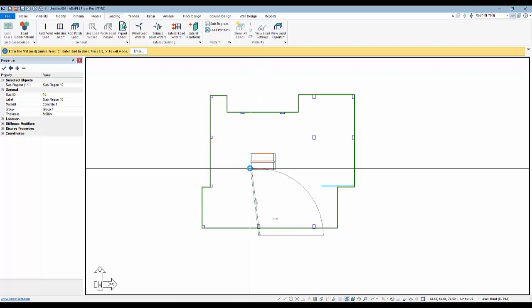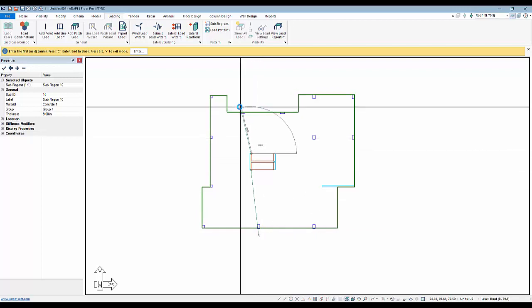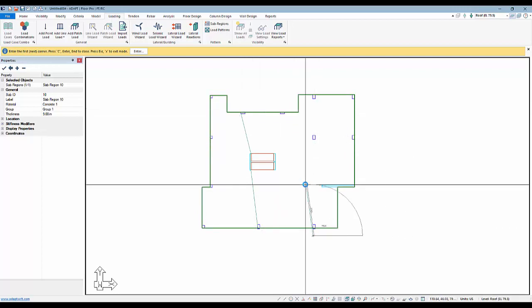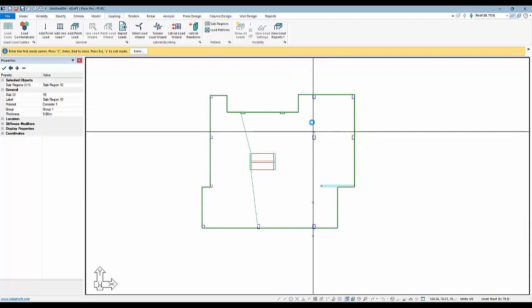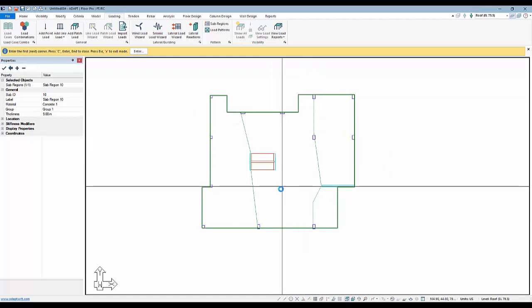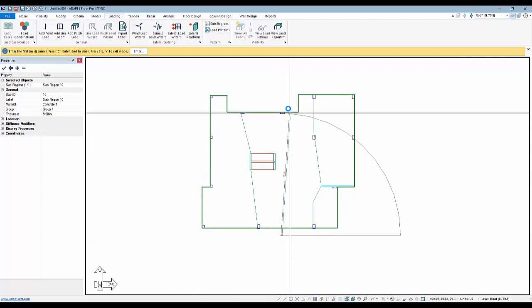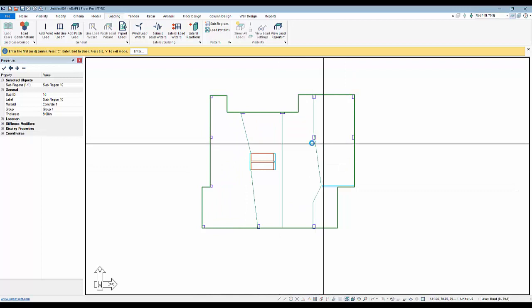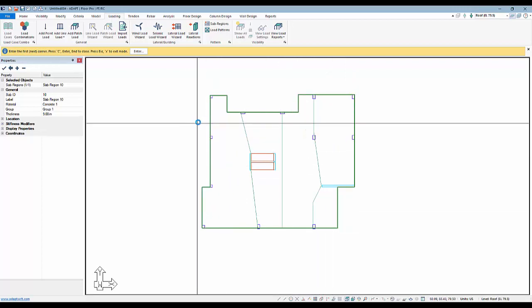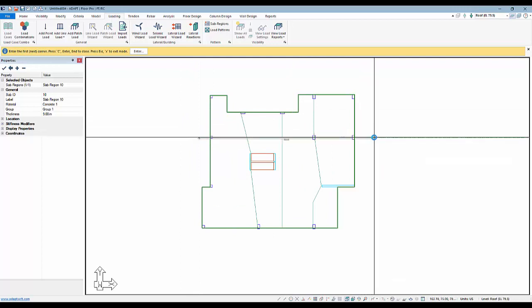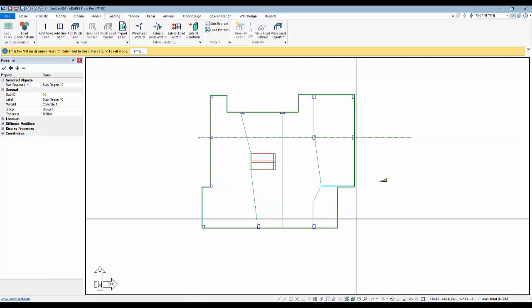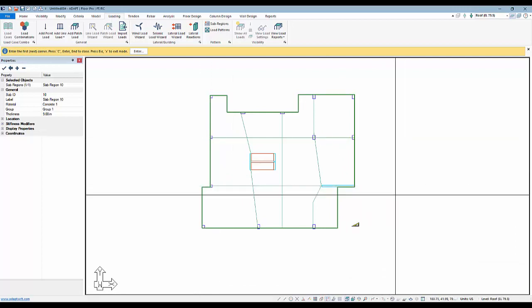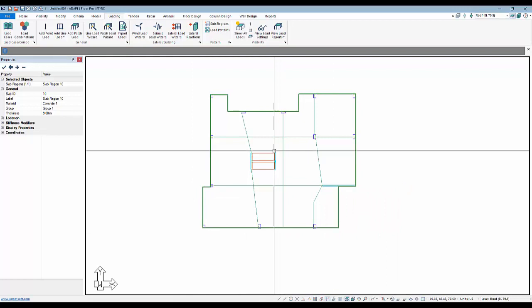So I'll select, for example, something like this. You could put these in orthogonally also. There's no requirement to do what I'm doing here. So we'll just have 4 strips here. And then in the other direction, I'm going to add these lines. If we want these orthogonal, we can actually use the snap orthogonal mode, like so. And so we have our subregions.